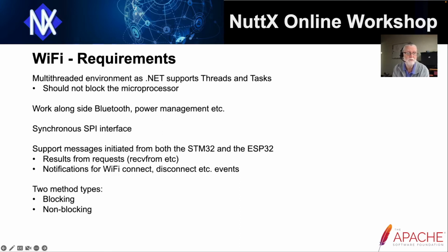So we could fire off from, say, the .NET application. We could say, I'll connect to the Wi-Fi interface, do it non-blocking, and just let me know when the connection's been made. So in that case, we would send a request from the user application through the .NET libraries that we have into NuttX to the ESP32 to say, connect to the Wi-Fi, raise an event when it's done. And when that request has got to the bottom layer and into NuttX and it's been passed over to the ESP32, we will immediately return so the user application can carry on working.